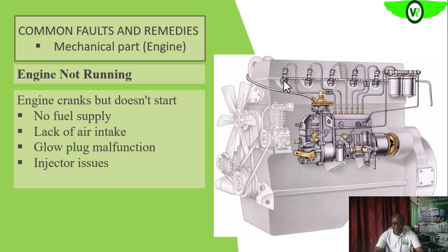That is, before we get to the required pressure on the nozzle pipe or this line, the nozzle would have opened up. So you see it delivering liquid fuel instead of atomizing the fuel into the cylinder, flooding the cylinder with too much fuel. Remember we are talking of diesel, that can also affect the engine starting the combustion process.